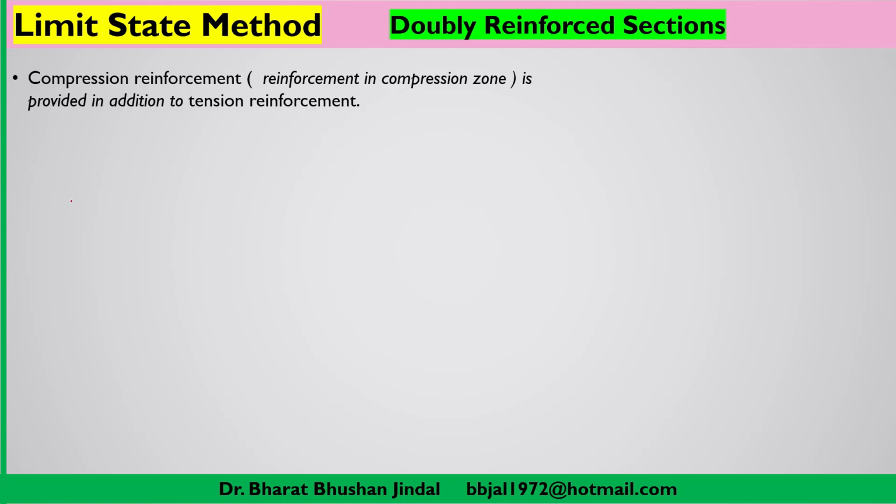Now compression reinforcement, that means reinforcement which we provide in the compression zone. In a simply supported beam, above the neutral axis we have to provide steel also, and that will be in the compression zone, along with the steel which we provide below the neutral axis, that is in the tension zone. So compression reinforcement in the compression zone is to be provided in addition to the tension reinforcement.